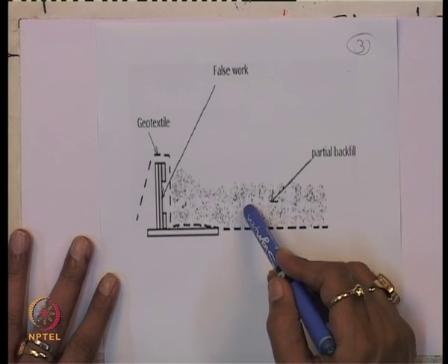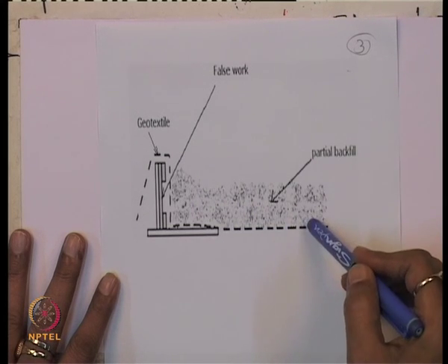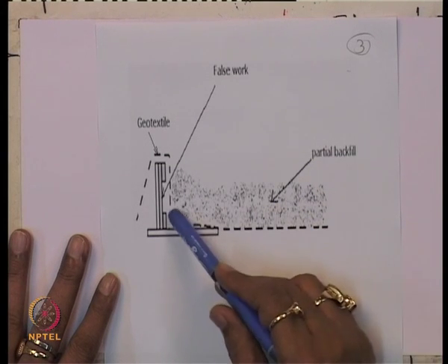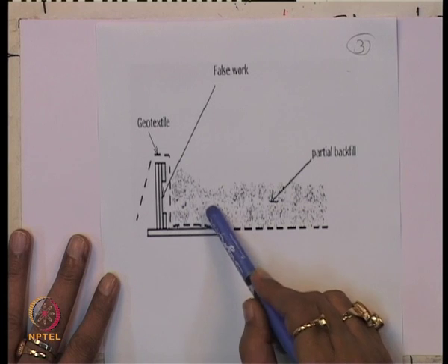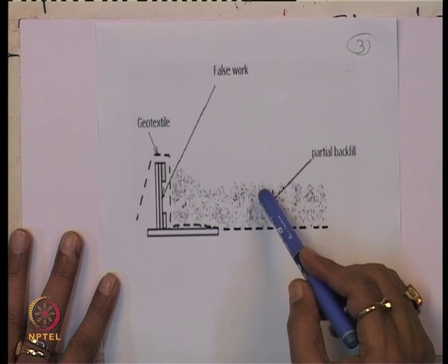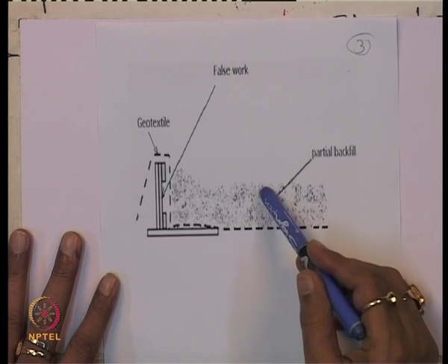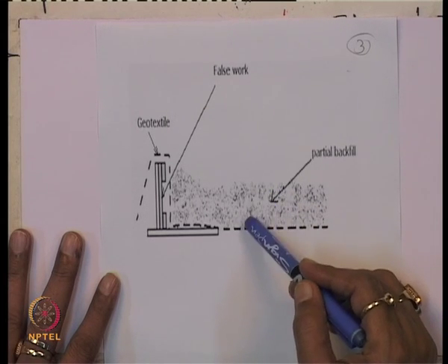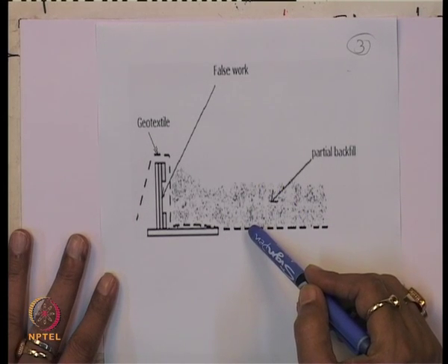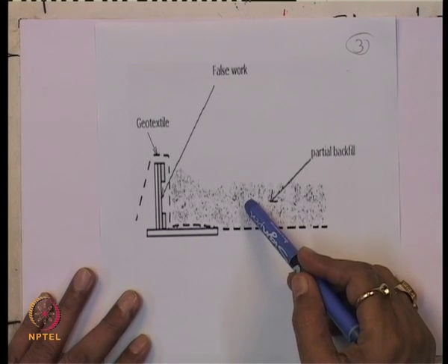Now you are placing this backfill material, up to about 200 millimeter to 400 millimeter, and compact it with a lightweight hand operated vibratory compactor. But you have to maintain the depth of the backfill material within 200 to 400 millimeter, so that the geotextile material may not be damaged during the compaction. So you should maintain this height.